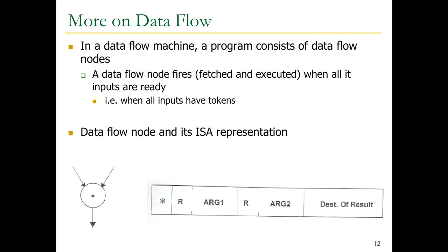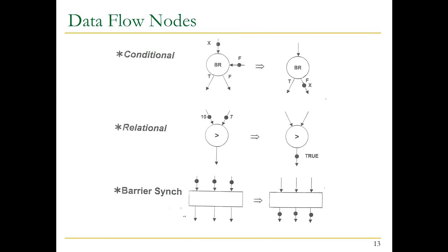So if you have a Dataflow node over here as the destination, you're sending it to the left one. So I'm sending to this instruction that's at memory location X, and I'm sending the left operand. And when that happens, there's some logic that sets this bit to 1. And then there's some other logic that determines the readiness of the instructions. So it's a little bit complicated. Now you can see how things go.